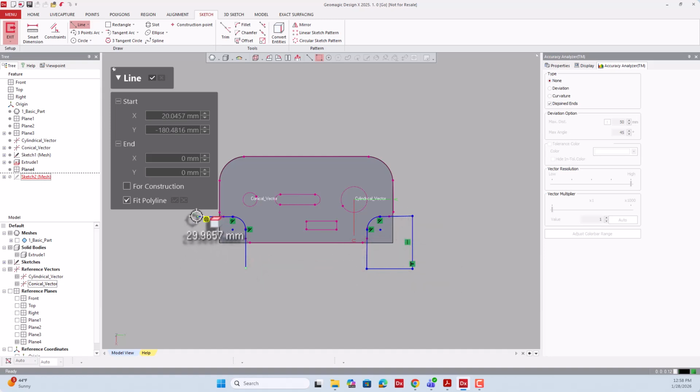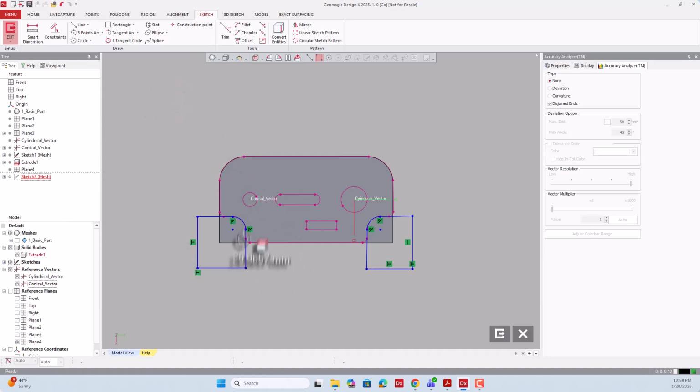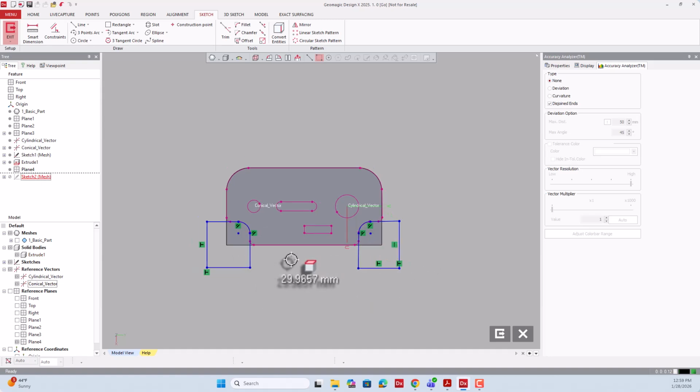So we're going to do the same process here to close out this side. Hover your mouse on top of the vertex. You see a coincidence icon. Single click. Now drag down. Click here. Now hover over the top of this particular point. You see the coincidence icon. Drop it. So here, right away, you get this particular sketch. It's a closed profile now.